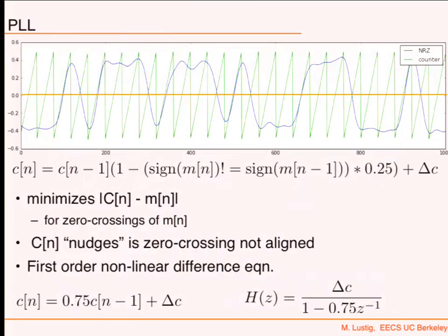And actually, you can show it. Here's an example of the signal coming in. When I'm not locked, you see that the 0 crossing here is not locked to it. But then as you move along, it starts getting locked, and now it's better, now it's almost perfect, apart from noise. So it starts locking to it.